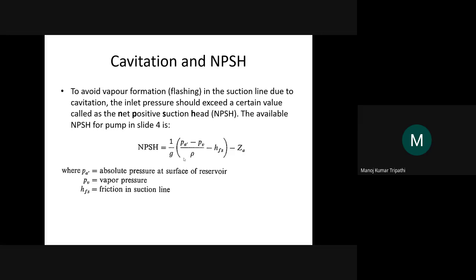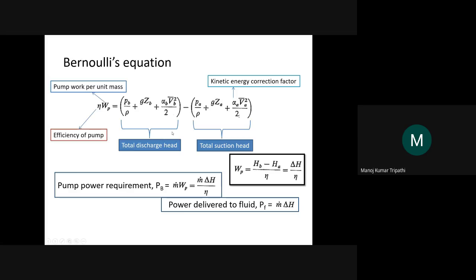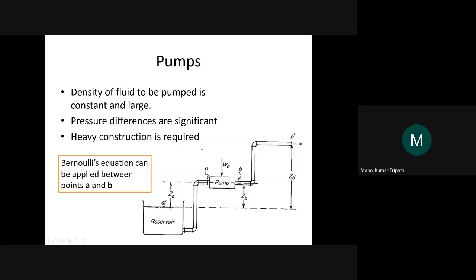And why is that? We discussed this term cavitation in some earlier classes. This can be considered to be a kind of boiling, where boiling occurs at room temperature. And why does that occur? Because of a pressure loss. If the vapor pressure is equal to atmospheric pressure, then the liquid can convert to vapor at that particular temperature. So this vapor pressure at the temperature where the pump is kept, if that matches with the pressure at the pump, then the liquid will cavitate and it will generate vapor bubbles.